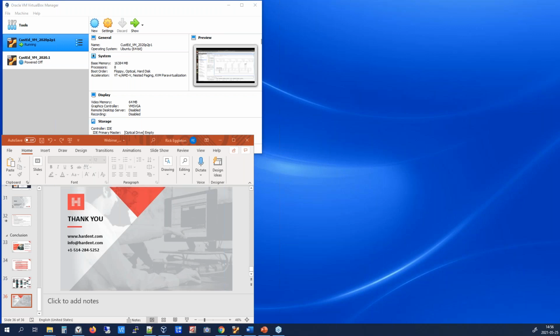So the first one comes in. Does the NoC support both memory mapped and streaming AXI interfaces? Absolutely. For the most part, it's AXI4 for the memory map, but it can also support AXI3 at the memory map side as well, and streaming is AXI4.